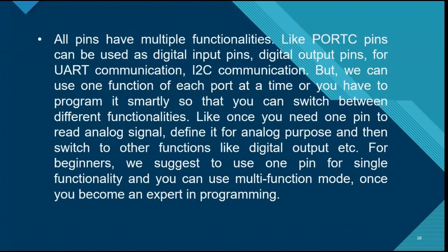All pins have multiple functionalities, like port C pins can be used as digital input pins and output pins, for universal asynchronous receiver transmitter communication and I2C communication, but we can use only one function of each port at a time. We cannot use one port for many functions. And these microcontrollers are also used for analog and digital purposes. We suggest using one pin for a single functionality, not for many functionalities.